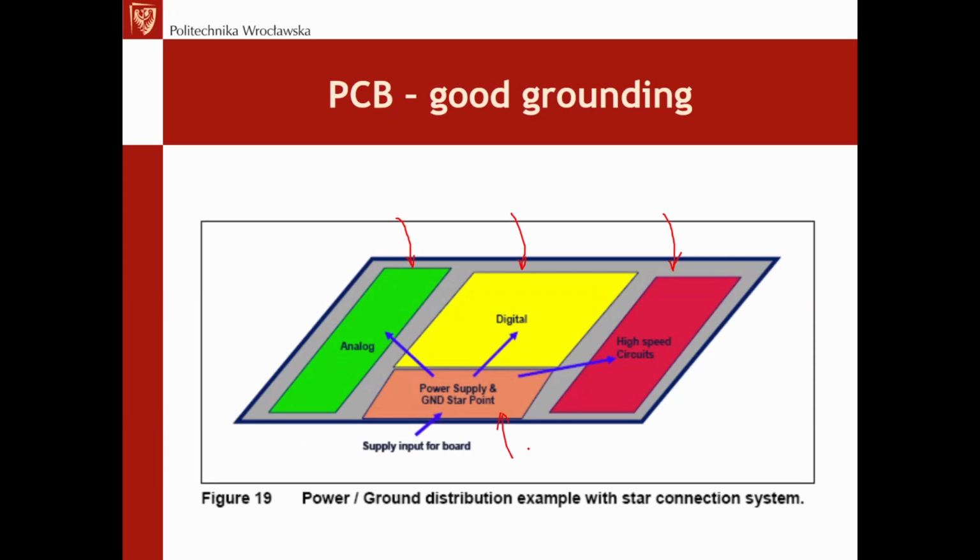The analog, digital: all the elements of low power, low frequency analog grouped close to each other, all the elements of digital origin close to each other, grouped in a physically constrained space. All the elements of group number 3, for high-speed circuitry, grouped with each other, and then all the elements of power supply and of high power as well,